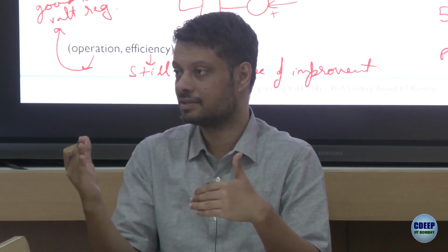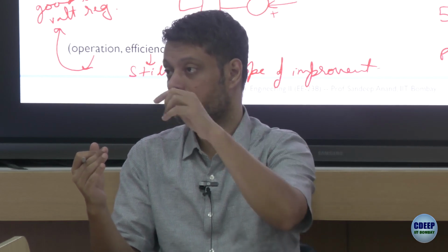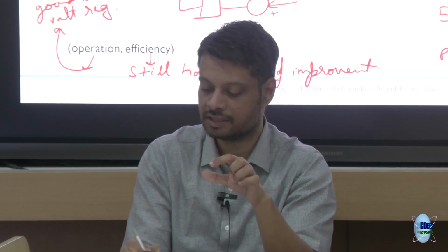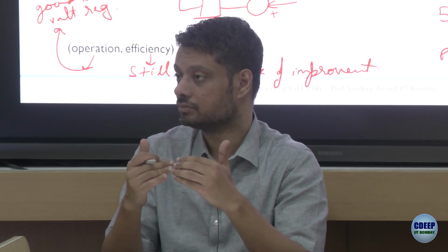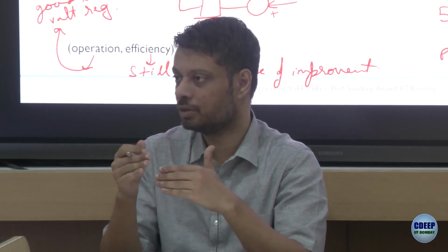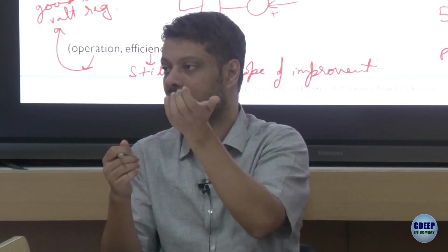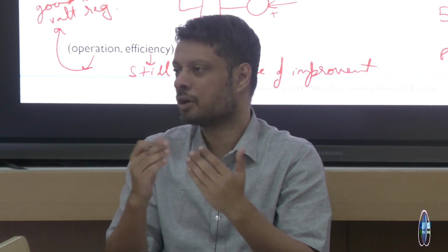If you have a load resistance, then you can increase the gate voltage and the output voltage will go up because current will go up. If you reduce it, assuming there is a small parasitic cap at the output, just imagine there is a small cap, there is no way to discharge it. If there's always a load, you have both the options. You can increase the output voltage by pushing more current. If you reduce the current, the voltage will come down. But if there is no load, then that option sort of goes away.